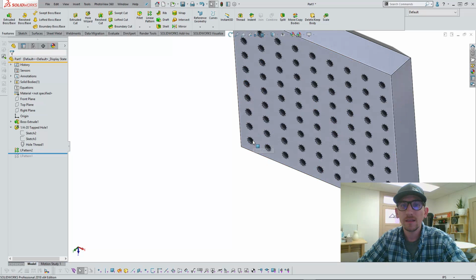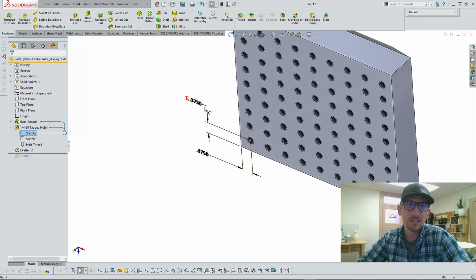You'll see that these holes just got shifted down and also shifted over. This just made my SOLIDWORKS part extremely smarter, right? And it's letting SOLIDWORKS model for me. Because if I did not do that equation, I would have to come in, update that dimension, and I'm like, oh yeah, that looks good. I might forget to come over here and fix this dimension.